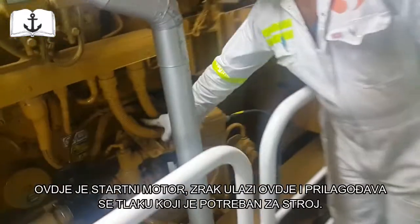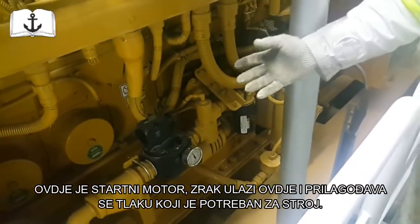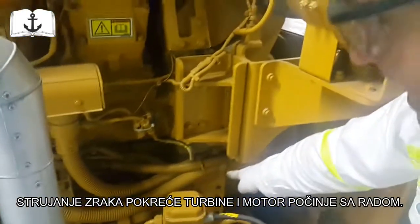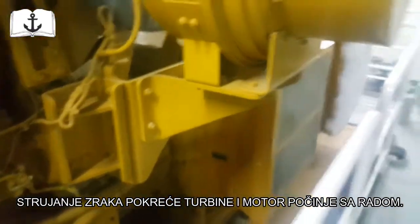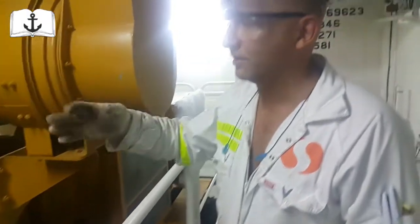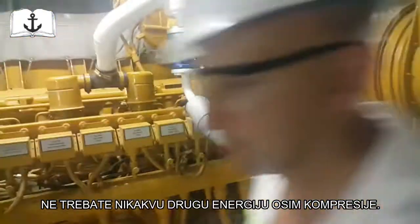This part is the starter motor. The air is entering there to the reducer because, for example, the engine needs 28 bar, let's say. Through the starting motor, the air power is converted by the gears, and it's going to the flywheel. The flywheel is a big toothed wheel on the shaft. So with the air, through these devices, you're spinning the flywheel and starting the engine. Fuel is open all the time. It's a diesel engine. You don't need any energy, just compression. Okay. Like a diesel car. Good. So it's quite simple.